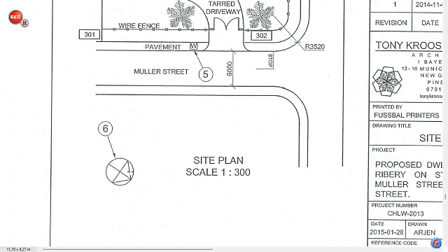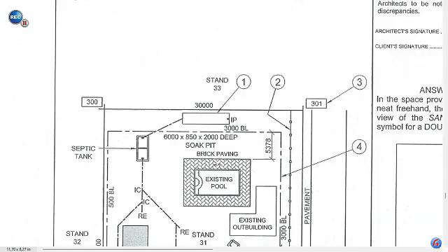So it's directly above. So we're looking at that particular distance here from the existing pool until the boundary line. From the swimming pool to the building line is going to be 5 meter 378, which is 5.378, and the 3000 BL refers to the distance between the building line and the boundary line. So these two values will be added, and that will give you 8,378. Converted to meters will be 8 meters